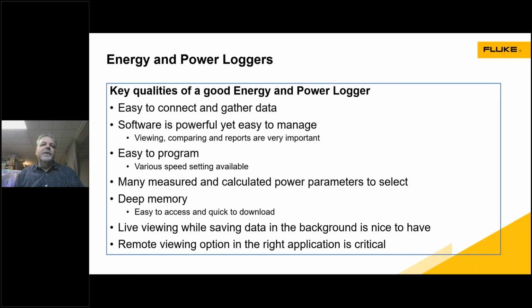So much so that, even though the hardware is solid, I would say the software functionality in our product is really awesome. And there's been a lot of time and effort put in to make that functional for our customers. The devices themselves have to be easy to program. And when I say easy to program, I don't want you to get overwhelmed that you're programming individual things. Really, it's just a case of picking the topology. In other words, is it 3-phase delta, 3-phase Y? Is it a single phase? What is the configuration? And then how often do I want to gather data? And then once I have that information, what parameters I want to measure. And once we have those 3 or 4 basic questions picked off of a selection table, you're pretty much ready to go.